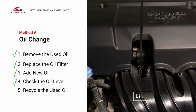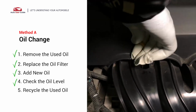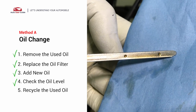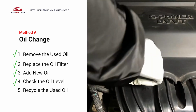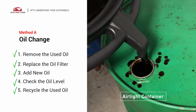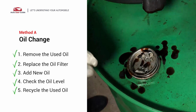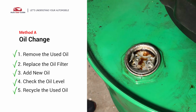To check oil levels, pull the dipstick out and clean it off. Replace the dipstick and pull it out again. The oil should be near the top dot or fill line. If it is close to the lower dot, you'll need to add more oil. Place the used oil from your collection pan into an airtight container with a screw-on cap. Make sure the oil is cool before transferring it to the container. Used motor oil can be recycled at most auto stores or at recycling centers.